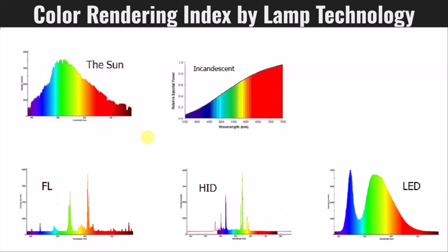Now we need to figure out how color rendering is influenced by correlated color temperature. Okay, so correlated color temperature, we know inherently incandescent bulbs were like 2000 to 2700 Kelvin. All right, you can't really move that, negotiate that anymore. Fluorescent naturally is mid to cool white. Okay, so that depends a little bit.